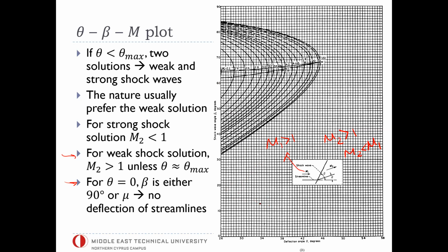But more importantly, for intake design, if you remember, we talked about these ramp type intakes generating, for example, one oblique shock, a second oblique shock, and maybe a normal shock. So the flow gets decelerated here, and inside the aircraft fuselage, somewhere here we have the engine, right? Somewhere here we have the engine.